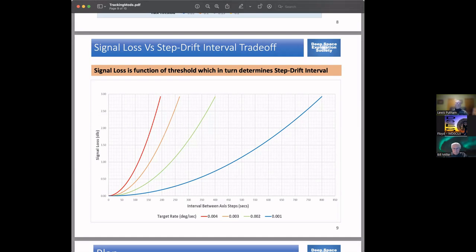I don't believe the motor is designed to do that. So basically the motor controller for the elevation axis won't let you go below 0.05. And to go to zero, you have to turn it off. And when you turn it off, then the brakes fire. That's really undesirable behavior, but it's what we got.